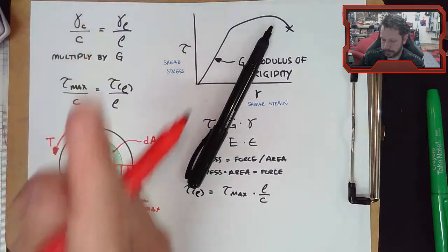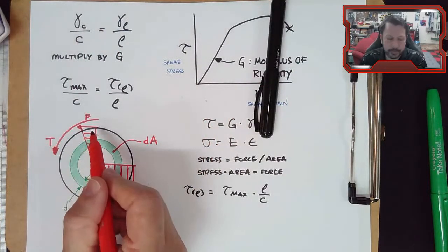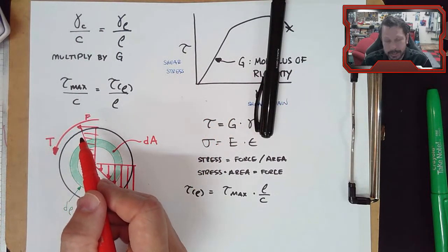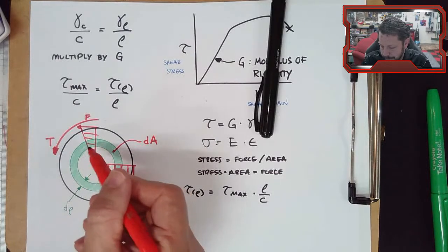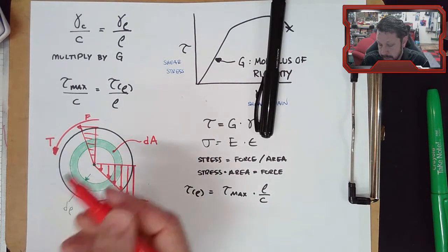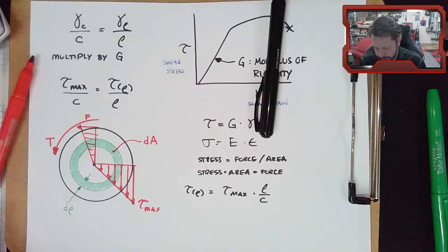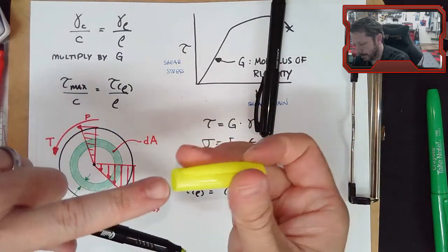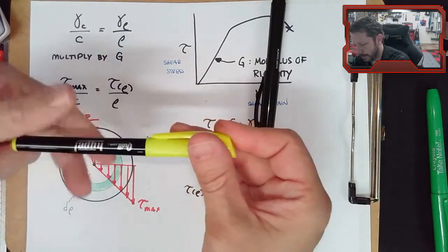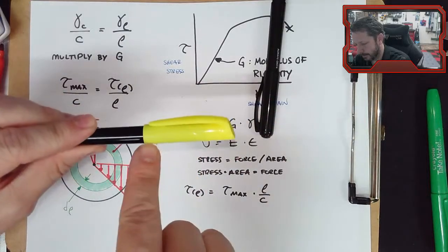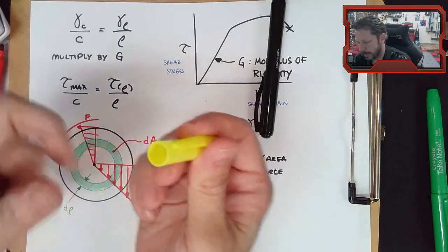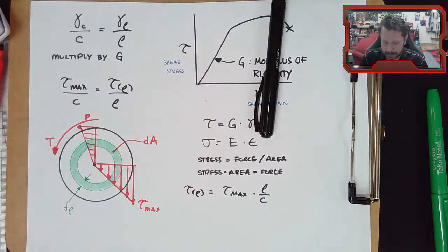And it would get larger towards the surface. Usually the force is applied at the surface. Obviously you can't normally apply force inside or something like that. Sometimes it is applied to the inner surface though. Maybe if this is a sleeve that slides over a pin and you're twisting this, then the force on this guy is actually applied on the inside. So you can apply them on the inner surfaces, but normally you can't apply them inside the geometry itself.